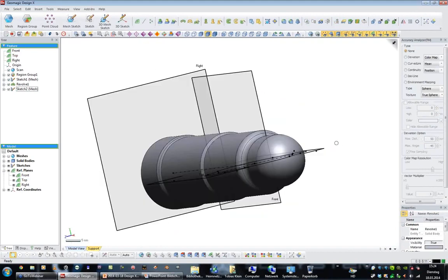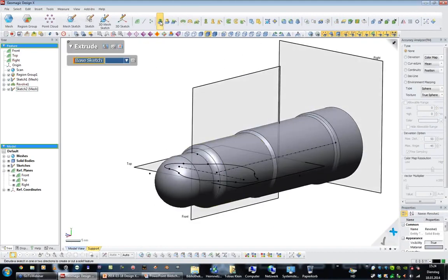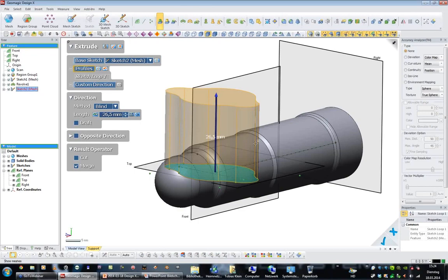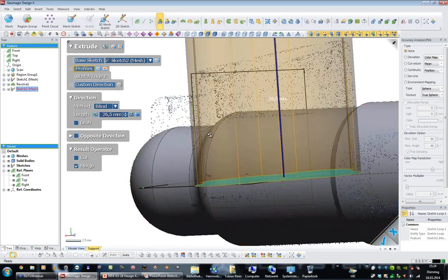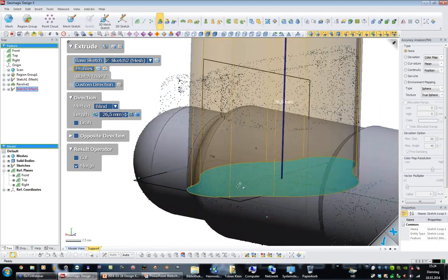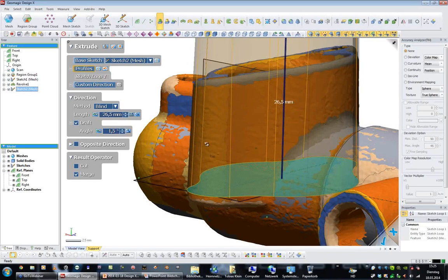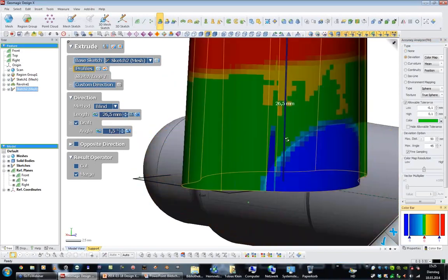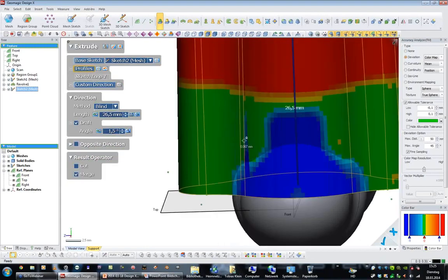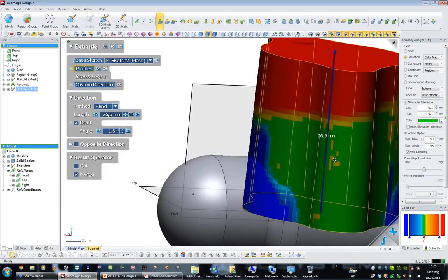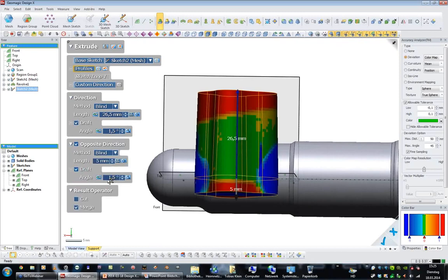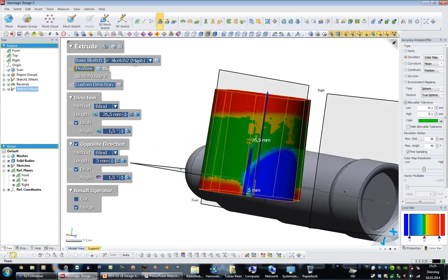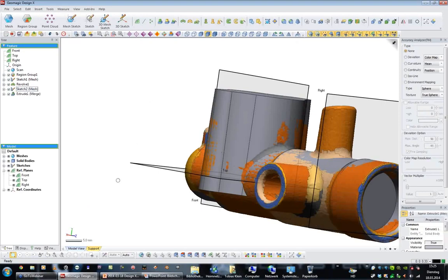So this is basically the 2D sketch. Now we can extrude this 2D sketch to cover this shape. Before, we checked a 1.5 degree draft, so now we can enter this draft here as well, and check if our assumption was correct, if everything is inside the green tolerance area. And we can also extrude to the other side. We have the same draft here, but in this direction. Okay, and it will be merged with the other part.